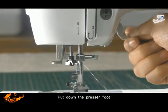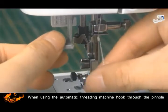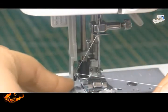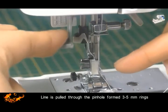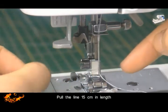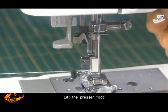Put down the presser foot. When using the automatic threading machine, the hook goes through the pinhole. Hang the thread on the hook. Then loosen the thread rod. The thread is pulled through the pinhole, forming a 3 to 5 mm ring. Pull the thread 15 cm in length. Lift the presser foot.